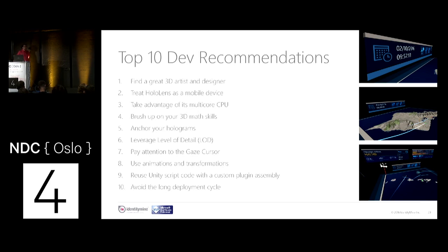And what I did here, I wrote a custom script where I can simulate the gazing and gestures already inside Unity. So I can do the same like the emulator does. I can use my mouse for gazing. I can use the right mouse click for air tapping. I can also use different gestures, but I can do this already inside Unity. And for every little change, I don't have to deploy it to the device or the emulator. It's a huge, huge time saver, right?